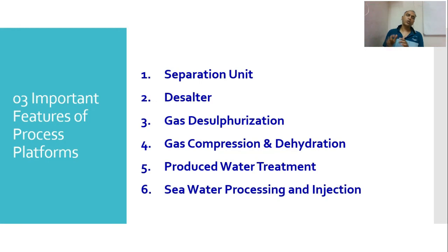So in order to avoid all this, the seawater processing is also required. So basically, four processes are there: separation one, second, processing of crude, processing of gas, processing of produced water, and again processing of seawater also, in case when produced water is less for injection. So this is the thing.